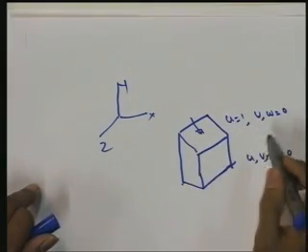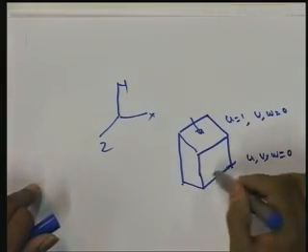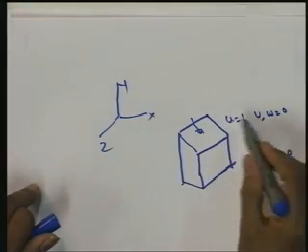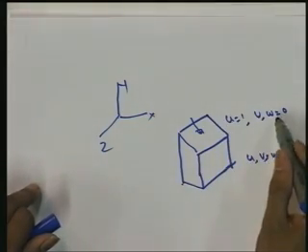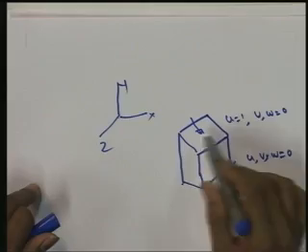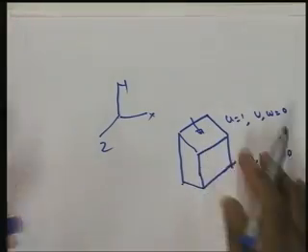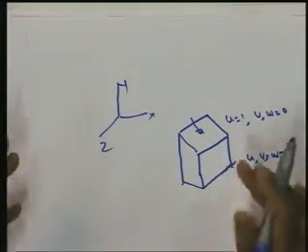Here the boundary conditions are u, v, w equal to 0 on all these sides, and on the top lid u is equal to 1, v is equal to 0, w is equal to 0. The initial condition we assume either as velocity 0, or if the velocities are known, then the initial conditions are given to solve these partial differential equations, the Navier-Stokes equations.